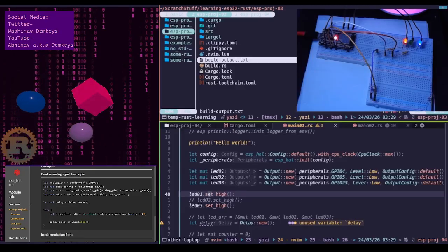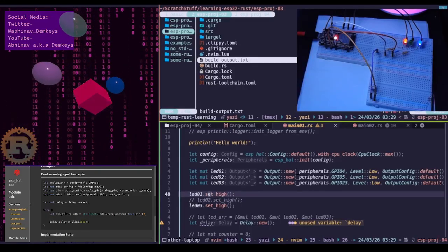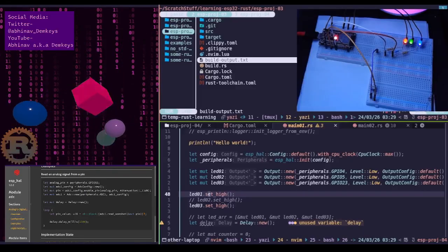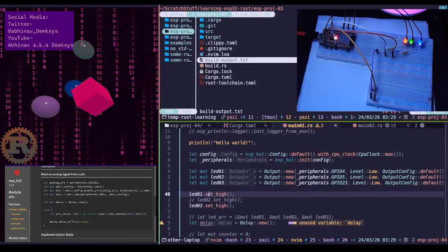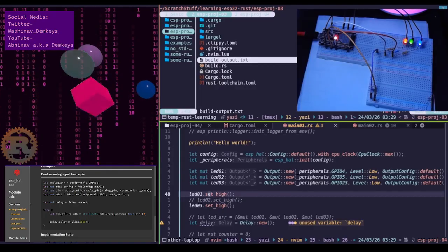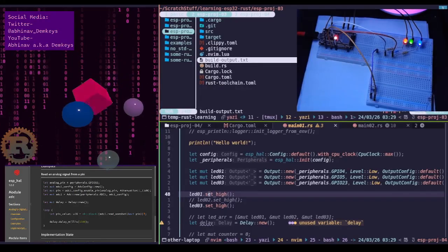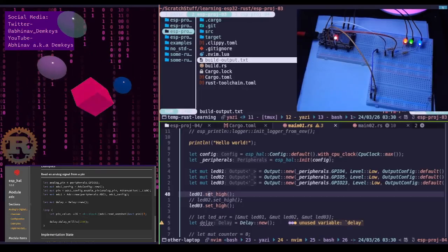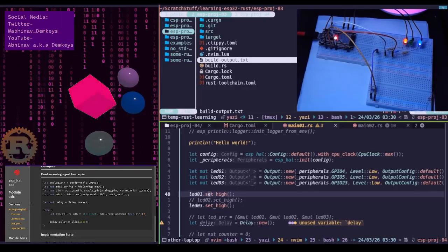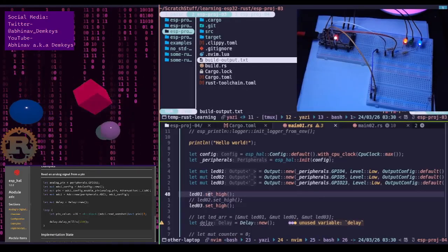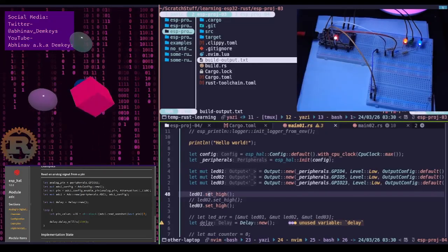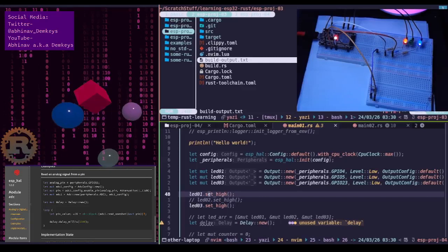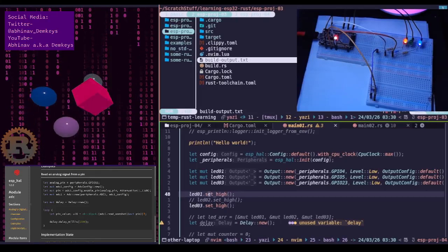It's a tiny amount of solder, just enough to apply to the surface. Then you touch both of these things together, heat both of them up together and use a little bit more extra solder, and that creates the bind. Because now that you have solder on both surfaces, the heat transfer is going to be much better than if both surfaces were bare.